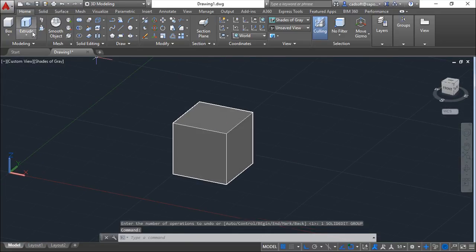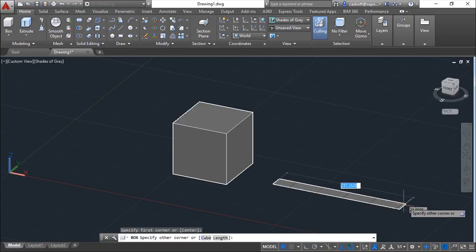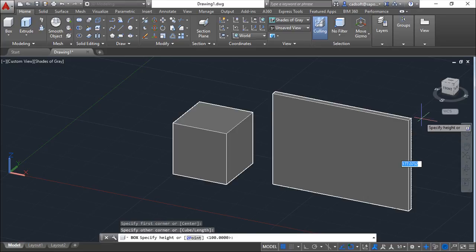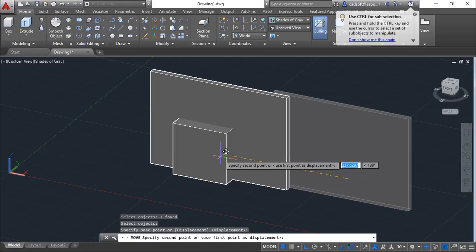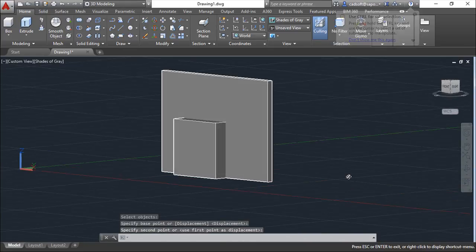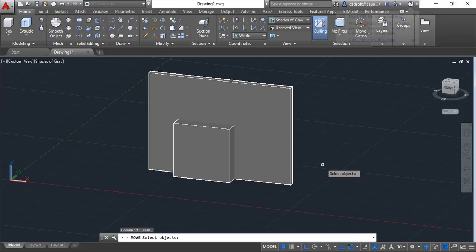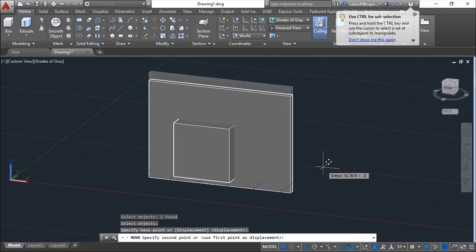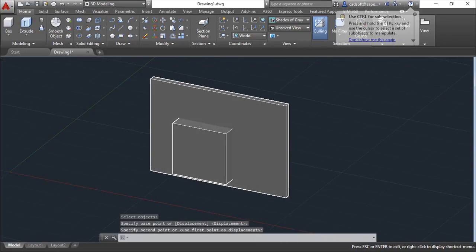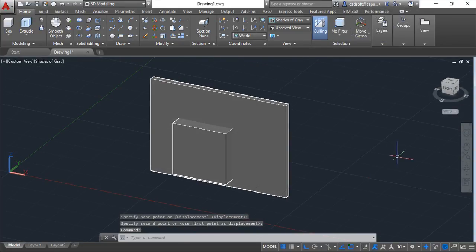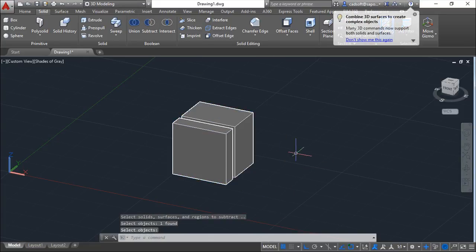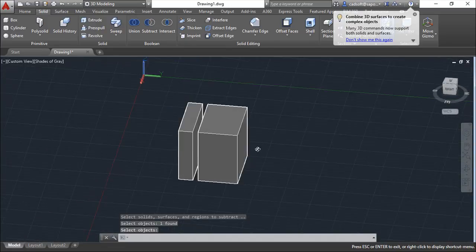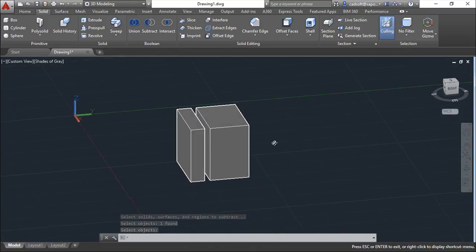For example, if I cross over this solid by this one, let me position this guy crossing this solid, and a little down. Now I can make the subtract, this one to this one, and I get the same solid, but it's split in two, so physically it's divided.